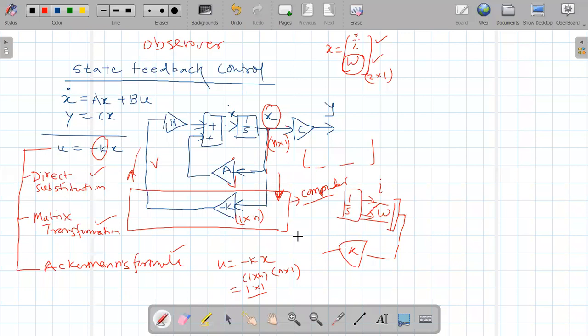That means here k will have some values measured from the system actually and some values calculated, obtained from the calculations. So we are giving speed directly from the tachometer and current we are calculating. This calculated current is called observed current, and for that we need an observer. So this is the concept of observer. I will show you it in more detail.